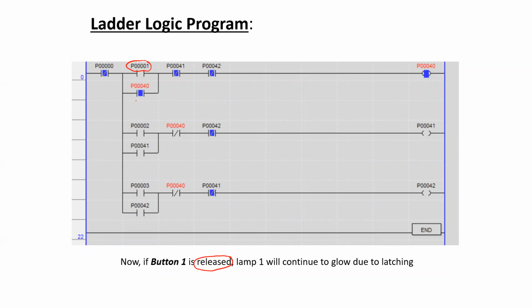But as a bypass path was already created in terms of the port address of the output port, following this bypass path, the output port P40 is still going to get a continuous signal, and the output device that is externally connected to this port will also have proper power supply. So the lamp connected with that port will still be glowing.